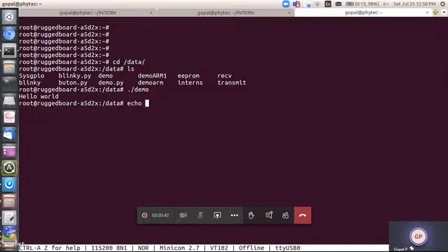We have calculations to do, but the vendor will support you. With the hardware manual that is available to you, you can straight away calculate the GPIO number. Here I'm showing the example with PC13, where an onboard LED is available, as we have seen in previous sessions. Now PC13, so I'm writing PC13 here. No, it won't accept.